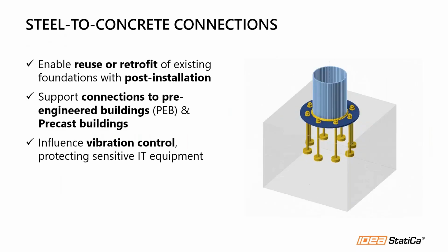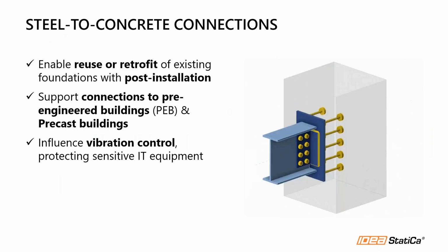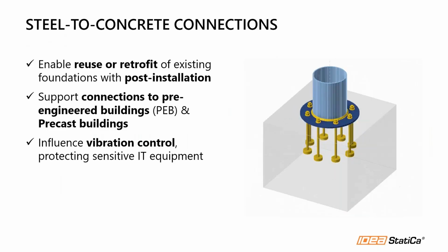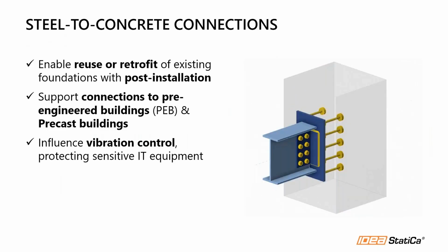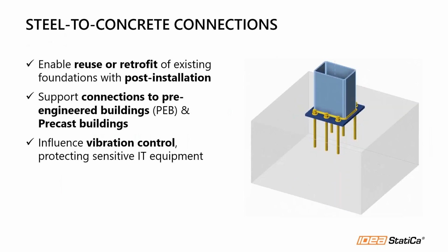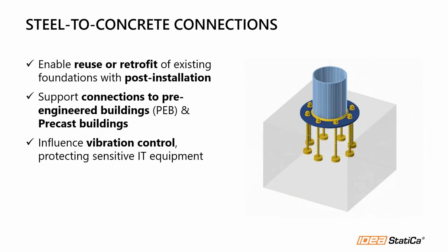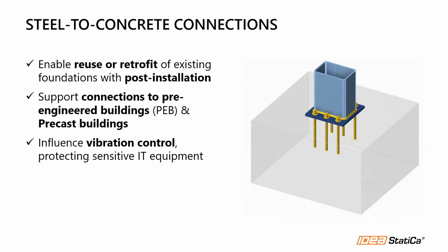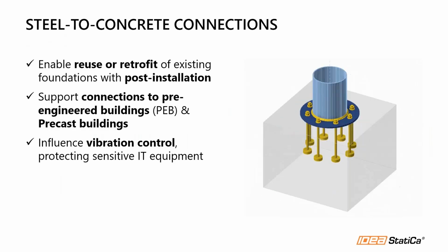Now, one important aspect of data centers is vibration control. Here, connection stiffness and detailing of the base plates directly affect that vibration performance, which is very critical for those sensitive IT equipment or server equipment that are housed in the data centers. So being able to model and analyze these connections with their real stiffness and their realistic behavior can greatly benefit the results.